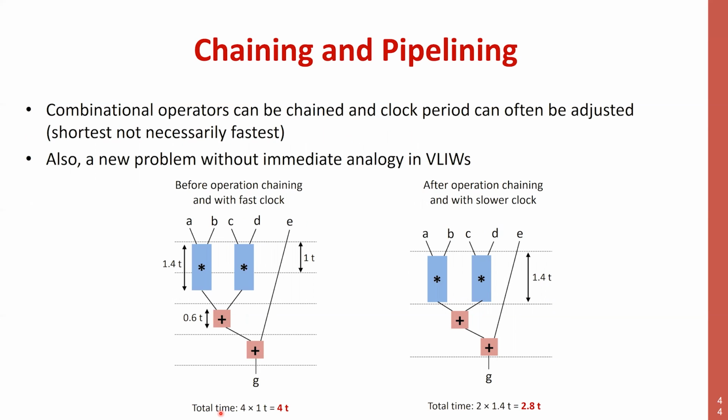This is the second example, corresponding to what we call the no time quantization in the first part of this course, and is an example where basically you have quantized everything to a given unit, 1t, whatever t is, 1 nanosecond or whatever, and you have quantized everything in clock cycles. You need 2 clock cycles for doing a multiplication, because actually the hardware takes 1.4 clock cycles, but you go to the ceiling, and the same for the addition, which takes 0.6.